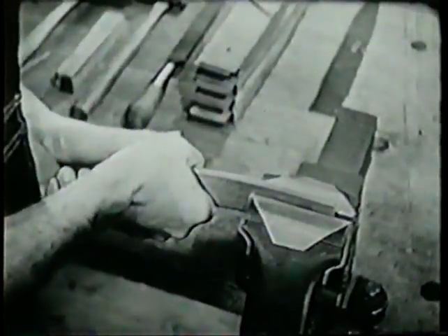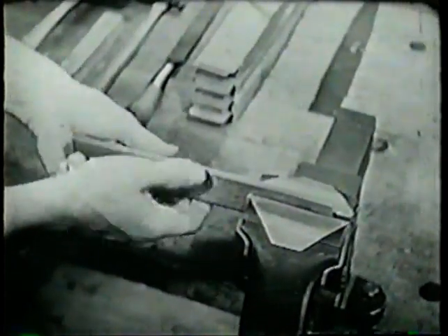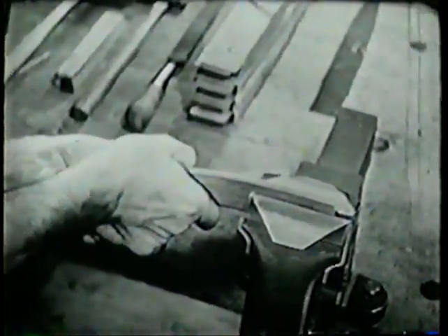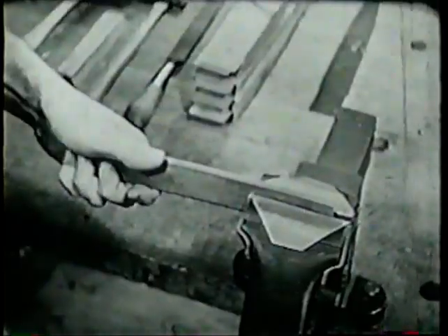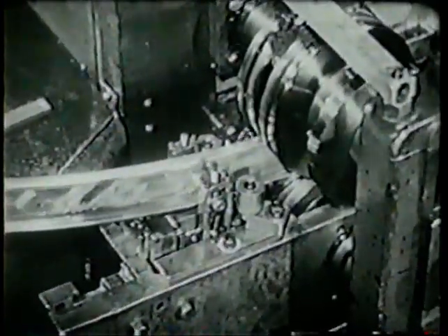Some forming operations require fully annealed or soft material. Operations such as bending may be performed by hand or by machine. This machine is used to bend metal sections that have already been formed, such as hat sections. Its basic operation is the passing of the part through a pair of rolls. As the part emerges, it is bent to the proper radius by a rubbing shoe, which is swung up to the required height.